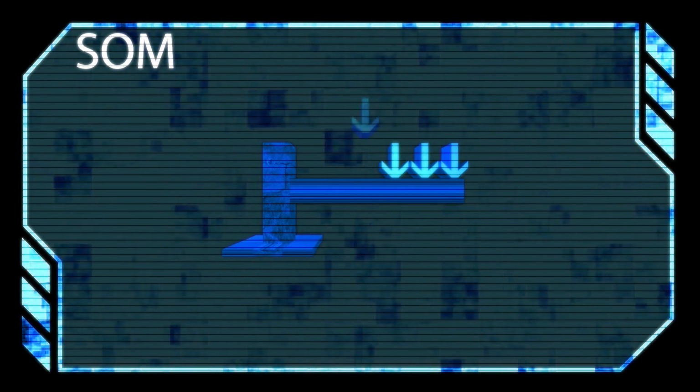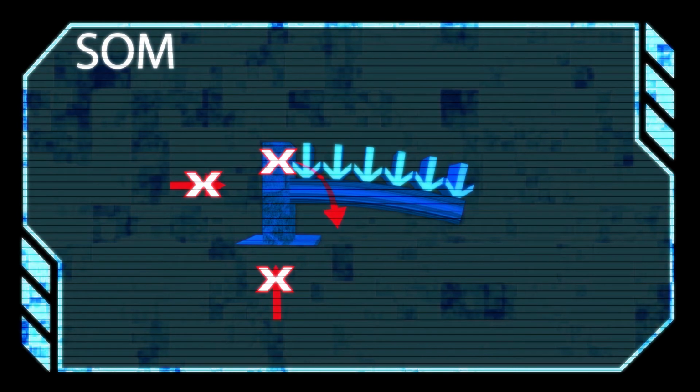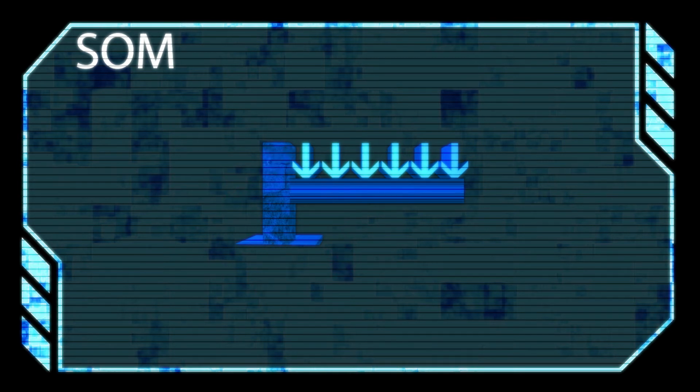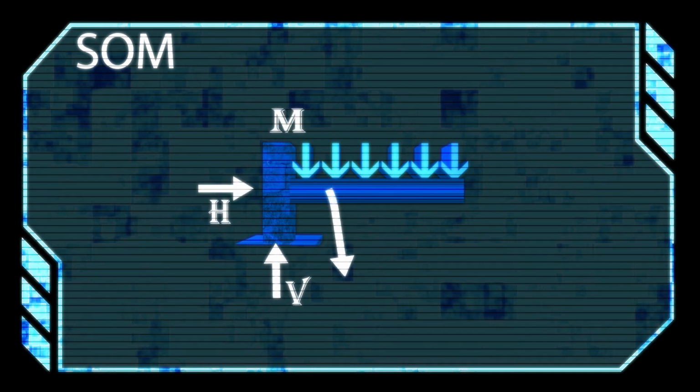Next, the fixed support. As the name indicates, the beam is fixed to the supporting element. So, as it is fixed, there will not be any degree of freedom at that joint. The beam is not allowed to rotate about the joint. It is not free to move either in the x or y direction. Therefore, 3 reactions are generated: reaction along the x direction, reaction along the y direction and rotational reaction, which is called the moment of resistance. That's all about the supports and reactions.